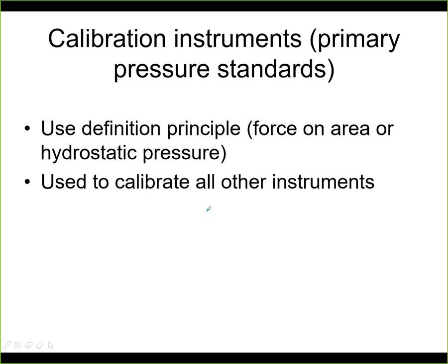But we will see next week that those instruments are not industrial grade instruments. They are either very expensive or they are very sensitive to damage, so they will not be used directly in industrial applications. So in industrial applications, in most cases, we do not use those calibration instruments. Those calibration instruments are used in labs or during production when you want to calibrate the other instrument. But then the other industrial instruments will use different principles, because the other principles will be more robust, more reliable, and less expensive.